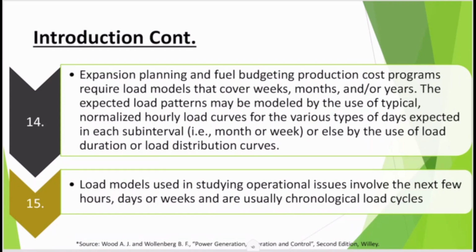Now expansion planning, because you need to plan your whole 1 year ahead strategy, expansion planning and fuel budgeting. Here I would like to deviate a little bit. Why do you need long-term planning? Why is short-term planning such as 1 day or 1 week not enough? Because just imagine the hydropower plants, the amount of water available to you. It's a continuous input, but those resources you have to utilize within a year, okay? Because once your water is discharged, then that year is gone. So you need to plan at what given point of time, how much water will be available to me and how much needs to be discharged. So how much energy will be available to me from hydro.